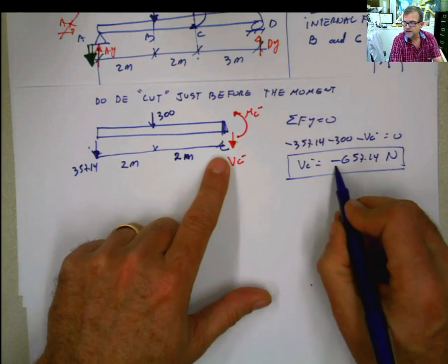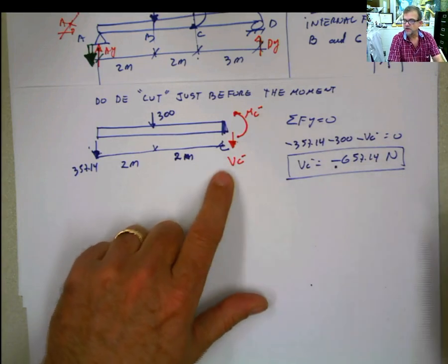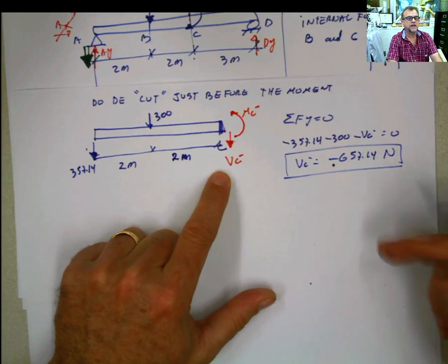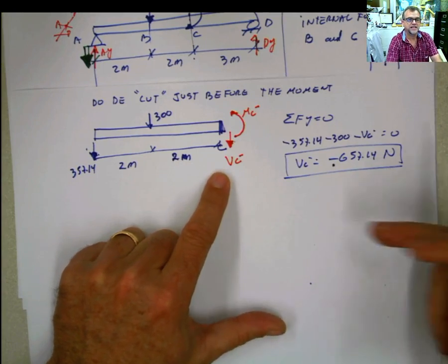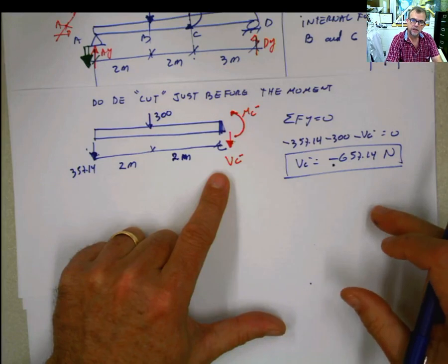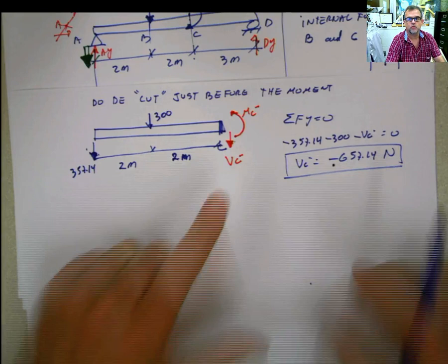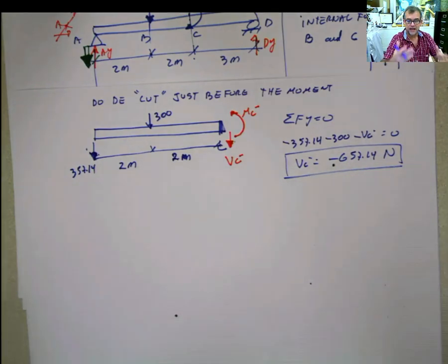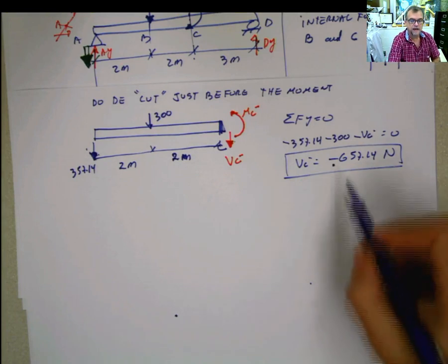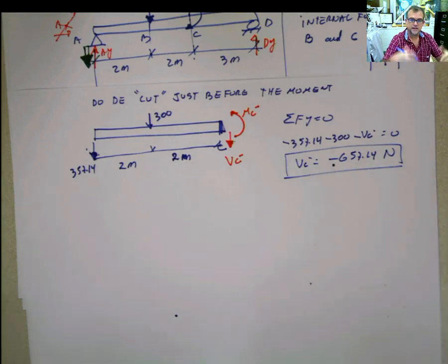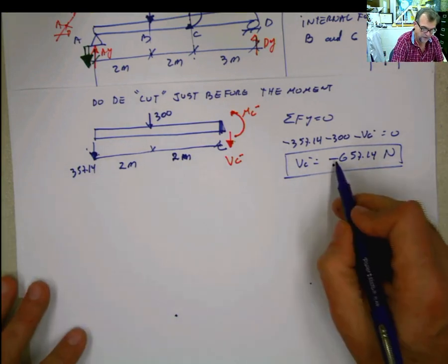That negative sign doesn't mean that I'm going to change the direction of the internal force. I cannot change the direction of the internal force. The internal force is created, is there, exists. The only thing is that I know that force is negative. So when I do my analysis, my design, my elements, my stirrups, my section, my everything else, I have to put my shear as a negative shear. But this is not the statics, these are future courses. But you keep it like that.